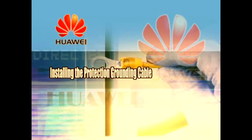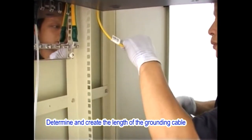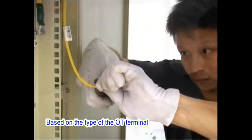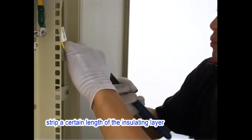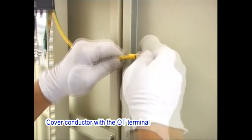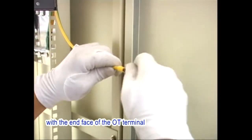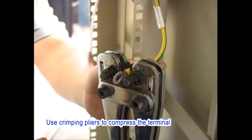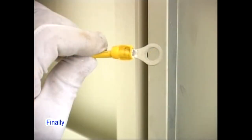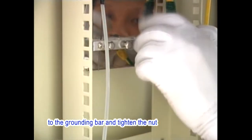2. Installing the protection grounding cable. Determine and create the length of the grounding cable based on the position of the grounding bar. Based on the type of the OT terminal, strip a certain length of the insulating layer off the grounding cable and expose the conductor. Cover the conductor with the OT terminal. Keep the cross-section of the conductor level with the end face of the OT terminal. Use crimping pliers to compress the terminal to ensure a reliable connection. Finally, properly fasten the protection grounding cable to the grounding bar and tighten the nut.